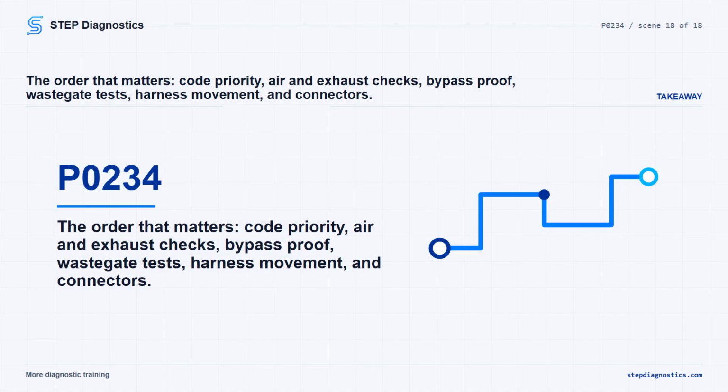If it is still present on this P0234 path, install a new turbocharger wastegate motor in question and reset KAM. If it is not present, the system is operating correctly at this time, and the concern may have been caused by a loose or corroded connector. Verify the repair and confirm P0234 stays gone.